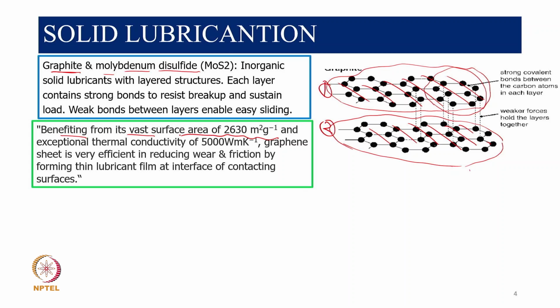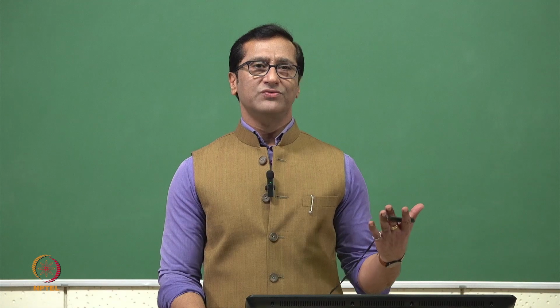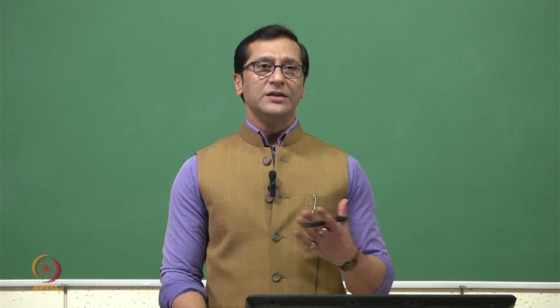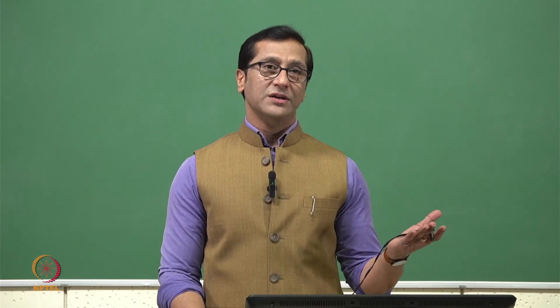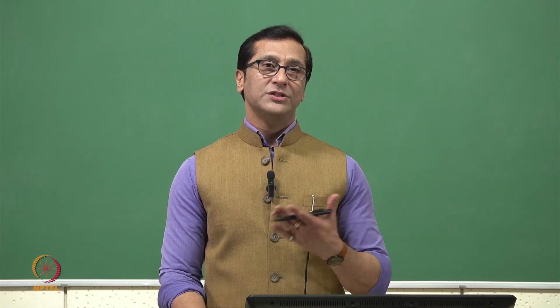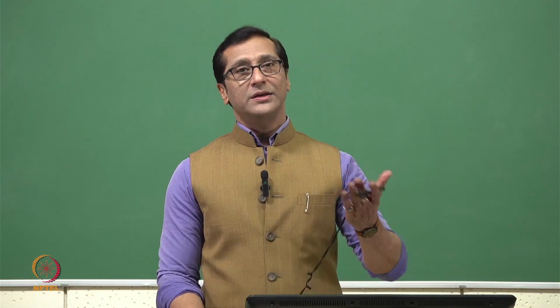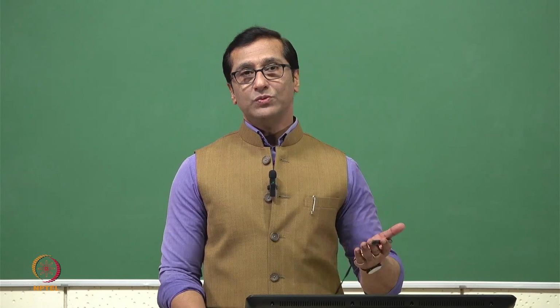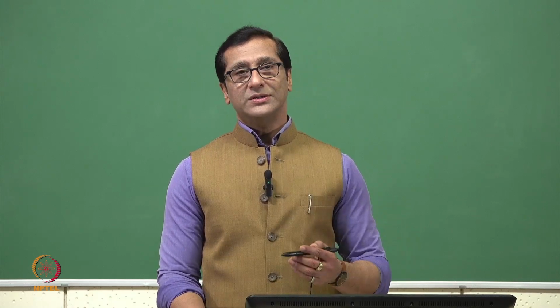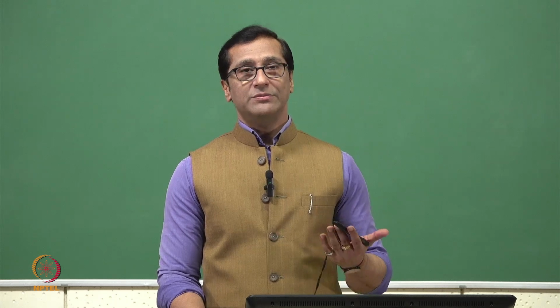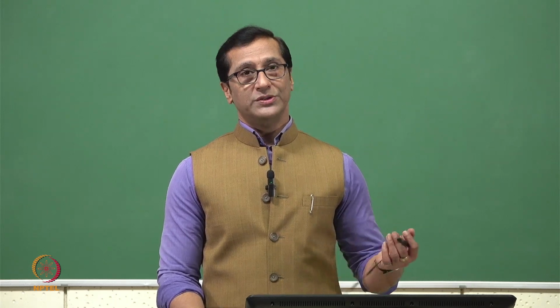Graphene, even if you take a small weight, its surface area is very high, and in tribology we are more prone to the surface area. We have a big surface area, lesser volume, and everything is a 2D kind of thing. If the surface area is more, we need a much lesser quantity of graphene. Even sometimes we use only 0.05%, and it really gives good results.